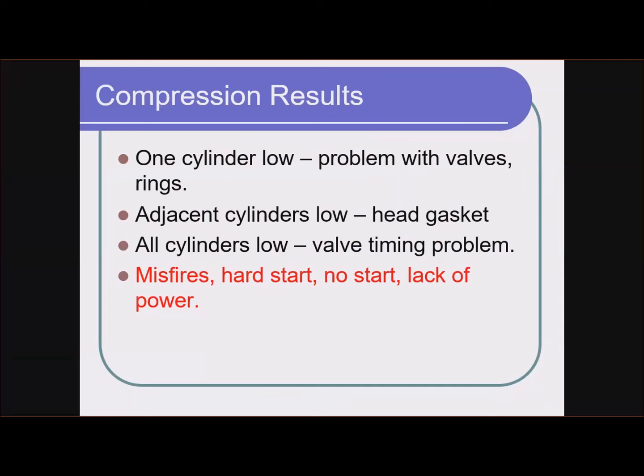So in general, and we look at all these tests that are available, you're going to do these tests from easiest to most difficult. On a lot of vehicles, compression test is going to be near the last thing that you do, right? Because it's typically pretty easy to check for spark. A lot of times it's pretty easy to check fuel. So you may never get to the compression test when you've already identified the cause of the misfire.